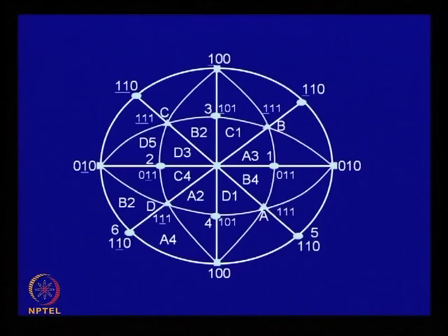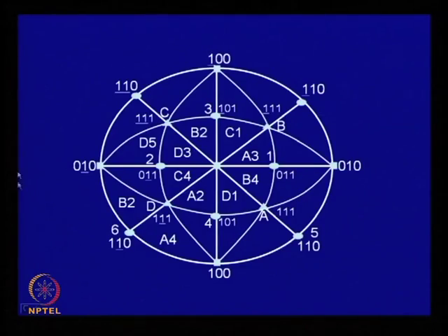Now, this slip system is very easy to visualize, and with respect to the standard projection, it is quite easily represented, and there is a very simple way of finding out which slip system will operate if you know the location of the tensile axis. And this is shown over here in this standard 0 0 1 projection. Now, in this projection, all the poles of type cube 1 0 0 and 1 1 0 are shown. So, these are the crystal axes 1 0 0, 0 1 0 and 0 0 1. They are the crystal axes, and they are axes of four-fold symmetry.